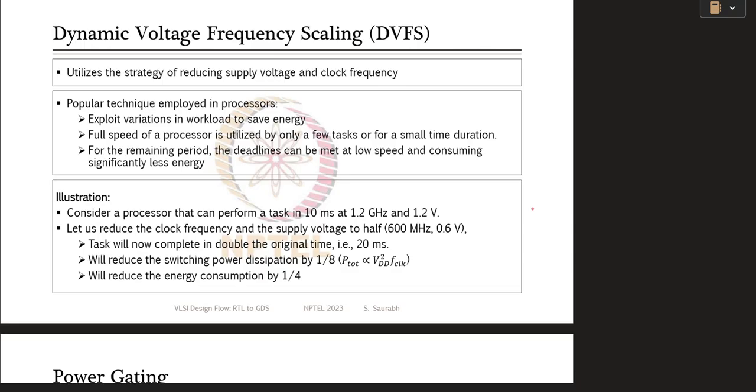what sir has taught here is that if VDD is higher, then CMOS gets higher power, so it will do its activity faster, like the charging of the load capacitance will become faster. Now if we are reducing the VDD, then the charging of the load capacitance will become slower. So we will require more than the usual time period to do the usual task.